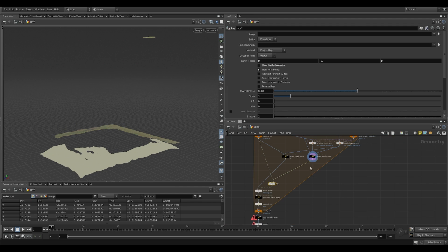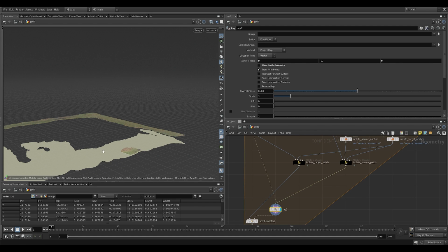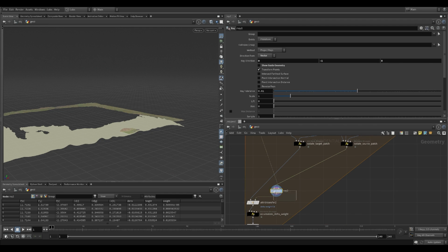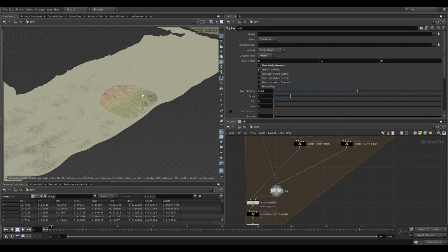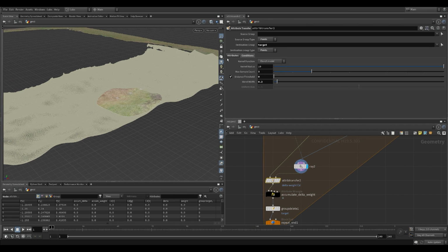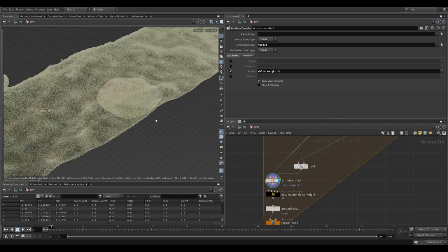Then we're going to do a raycast downwards against the target, because what's running through the loop is the target geometry as a whole. So this branch grabs the target as a collision geometry, and here we set the direction as a vector, and this vector direction is the downward direction. So that projected our source patch onto the target patch. Once it's projected, we could do attribute transfer with a pretty close distance. So here we're transferring over the delta, the weight, and the city. Weight and city is a bit obvious.